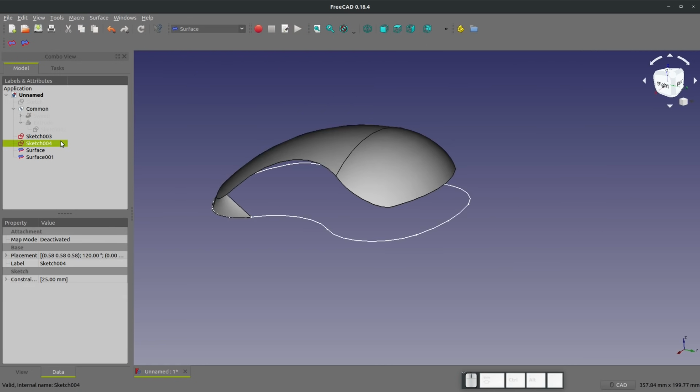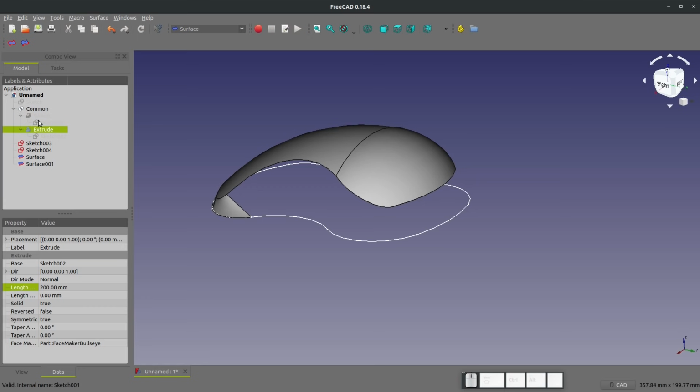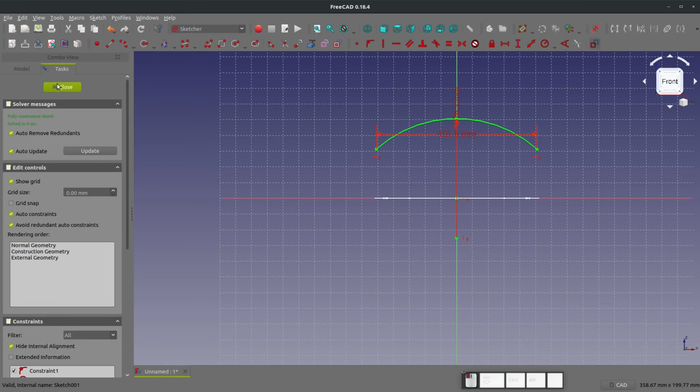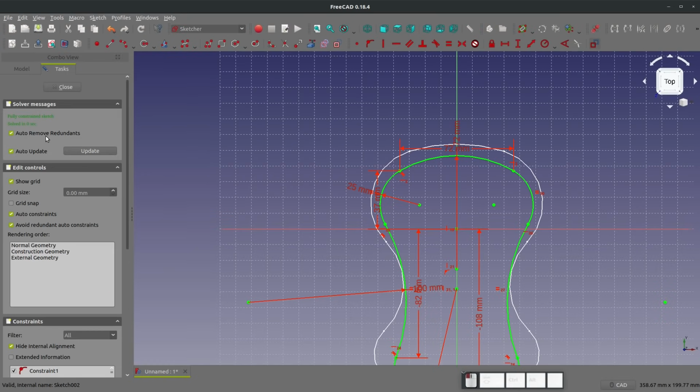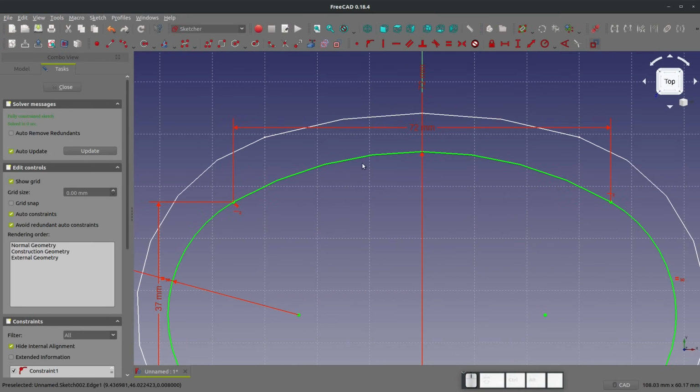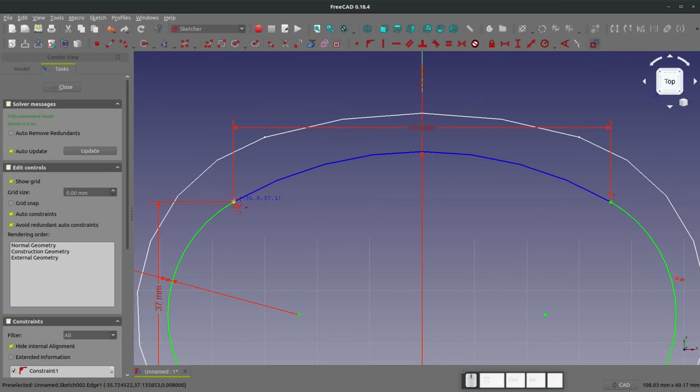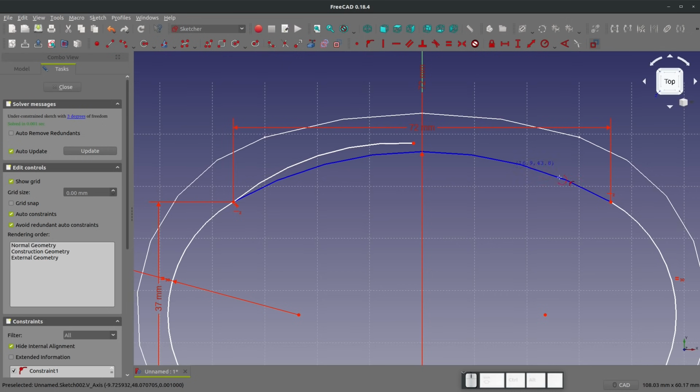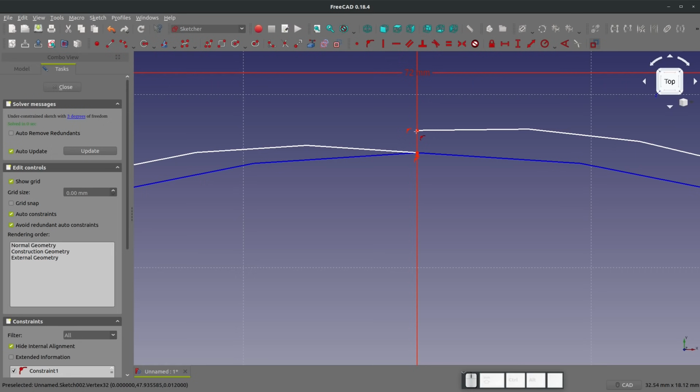What I'll do is go back to my original surface, and it should be sketch 002 again. And notice I have this arc that's going all the way across. So one little trick is to make this for construction and simply add 2 arcs in its place, and that way you don't lose any of your existing dimensions or anything like that. So I'll choose the coincident and go from here to here. We're going to make everything coincident to that axis and then to this arc.